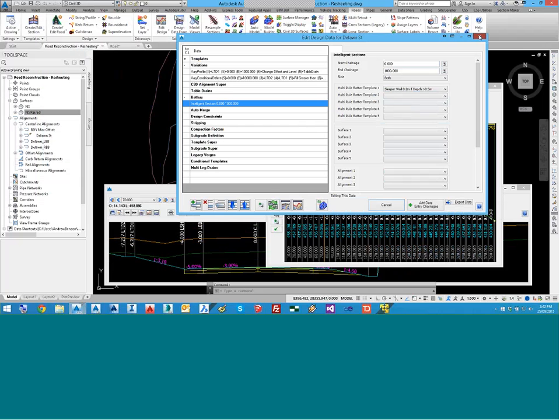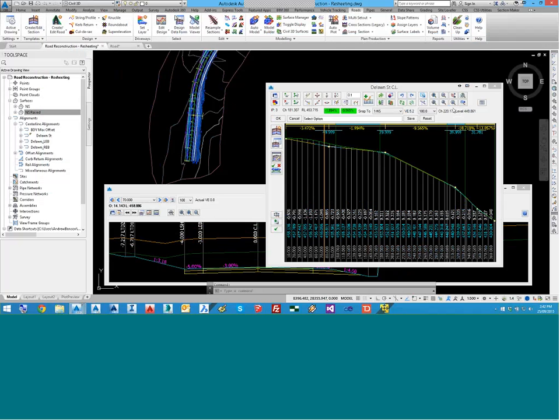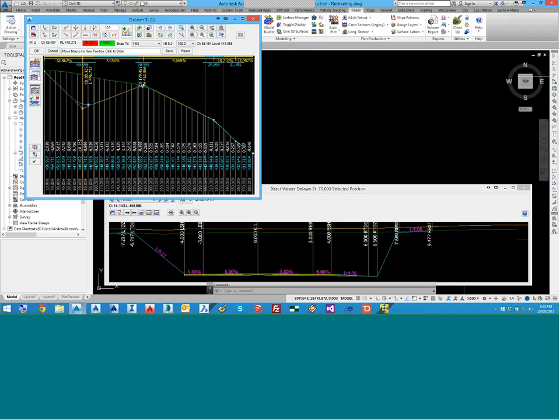Just on the model viewer, I actually set this up with a material. So there's that wall here, and you'll see that as I move the levels up in the profile view, my render just updates. This will give you a bit of an idea of how quick this new model viewer is. It's great to be able to check your design in a 3D environment so quickly, as opposed to just looking at line work in the drawing.